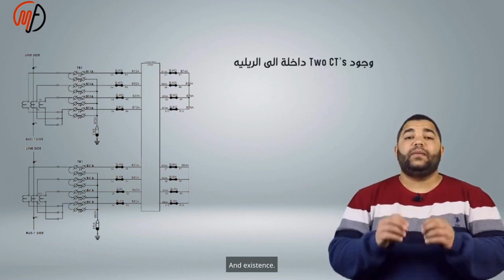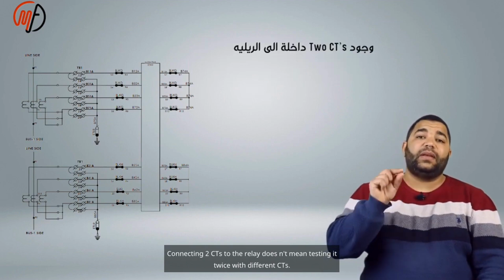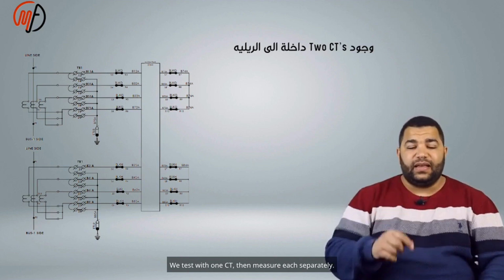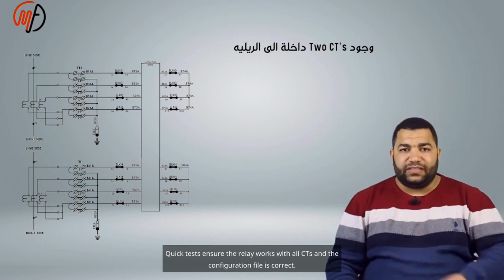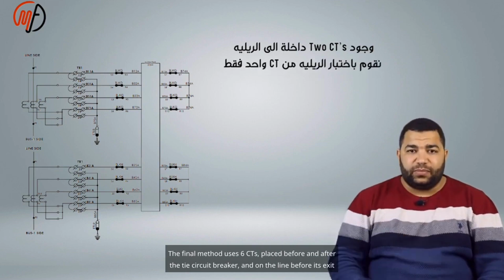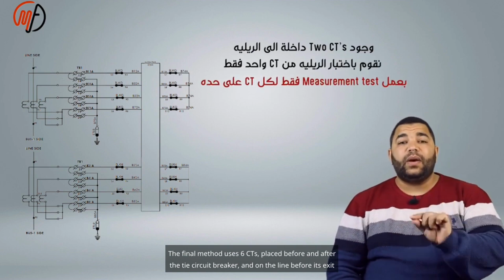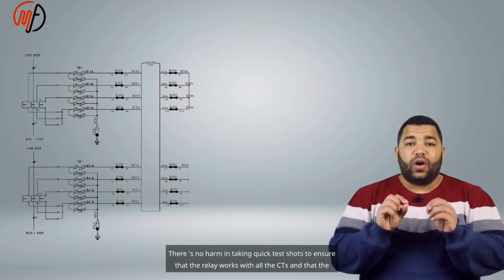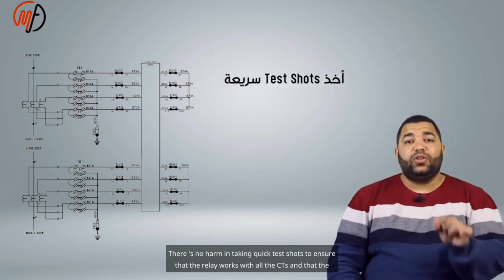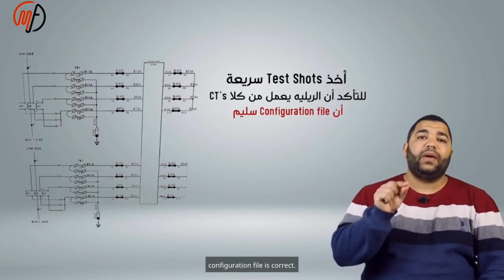Connecting 2 CTs to the relay doesn't mean testing it twice with different CTs. We test with 1 CT, then measure each separately. Quick tests ensure the relay works with all CTs, and the configuration file is correct. The final method uses 6 CTs, placed before and after the tie circuit breaker, and on the line before its exit. There's no harm in taking quick test shots to ensure that the relay works with all the CTs and that the configuration file is correct.